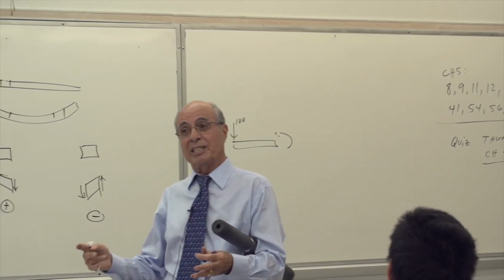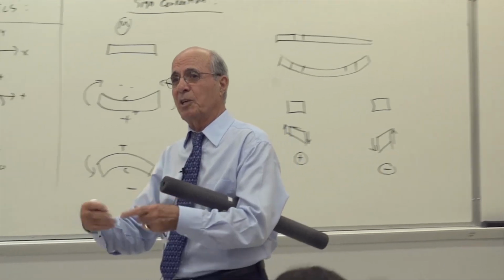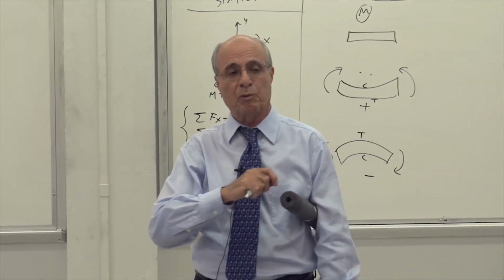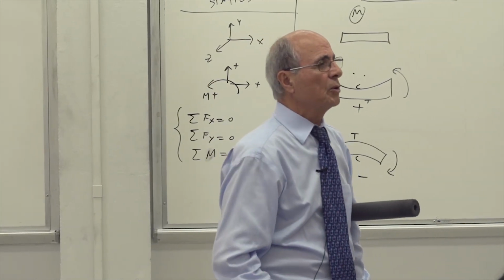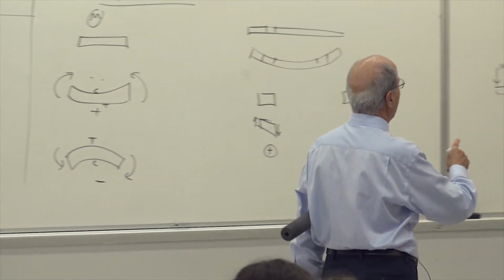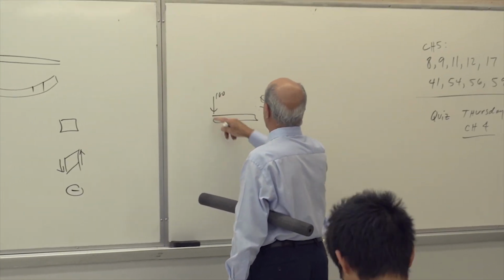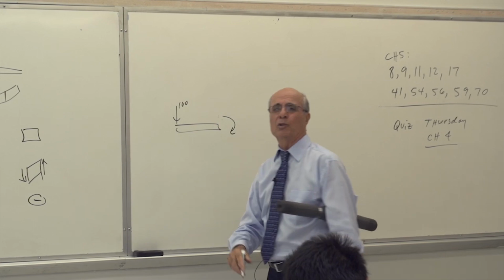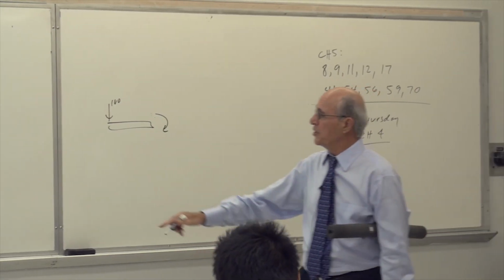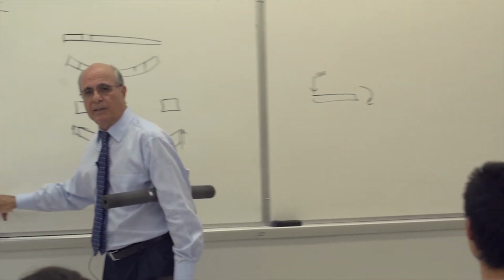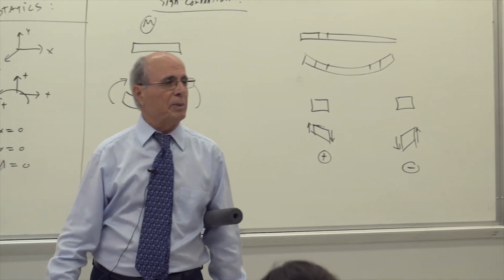So here will be the reaction equal, and remember what I just told you a minute ago, the mistake where you said I'm getting all my M negative. I said it's because you are not calculating the reaction. You have to put sum equal to 0, by the way. So this is very simple. I'm not going to do that. Obviously, if the action is like that, the reaction should be like that, which makes it negative. So the moment must also be negative.